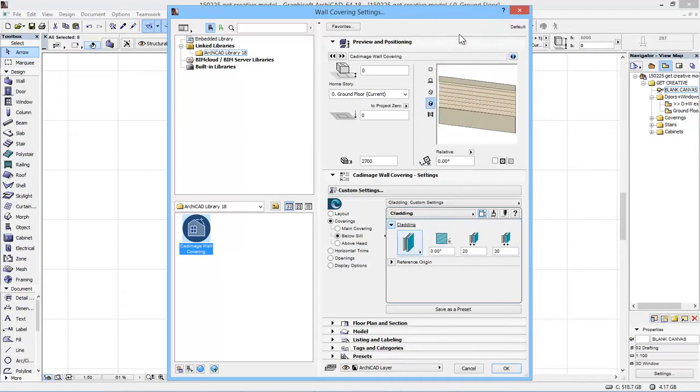For here, I'm just going to go for bricks and blocks, and we'll have an offset of 0. We'll say brick length, we'll actually do it block sized, so we'll have 450, 100 thick, 225 high, and we'll also have a 225 stack so that we get nice coursing that goes along through the building. Again, we'll set this for ground floor.